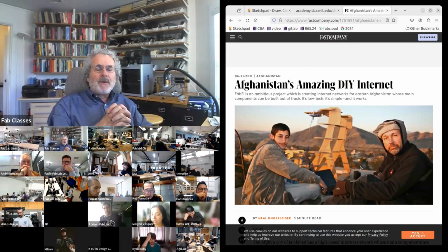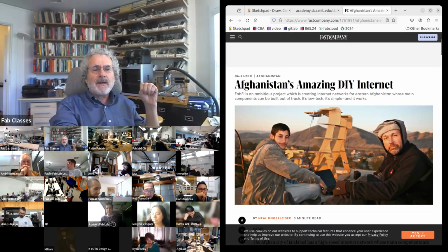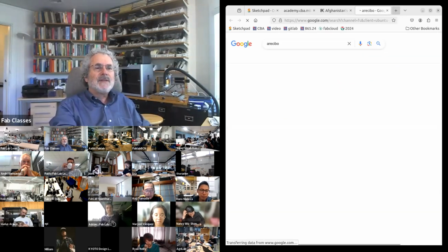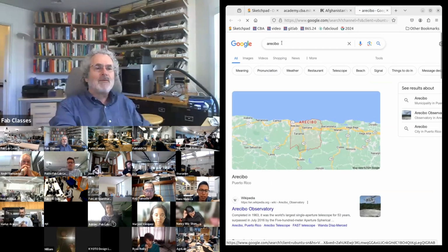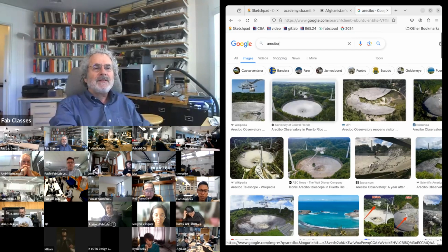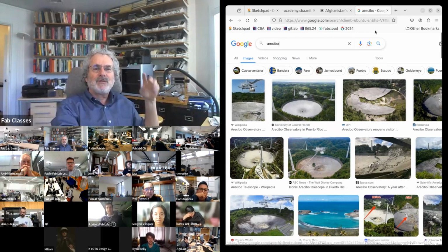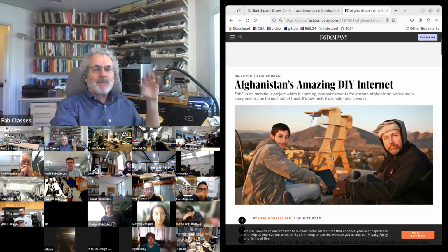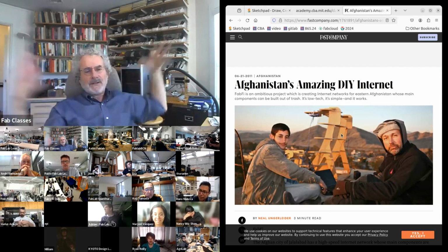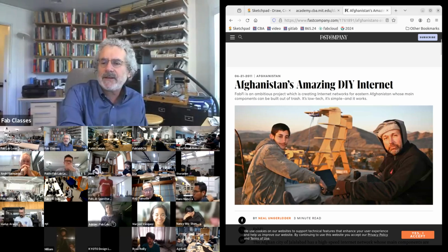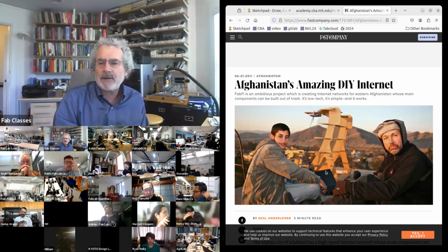And it experimented with a number of high gain antennas and radios. And what ended up winning was just making a parabolic reflector. So what you're looking at, sadly, Arecibo, the radio telescope failed, but this is a receiver at the bottom, at the focus of a giant parabolic dish to talk into deep space. This is a more modest version with the ShopBot make a large parabolic reflector and then put an antenna and radio at its focus. And that can do about a 10-kilometer link.